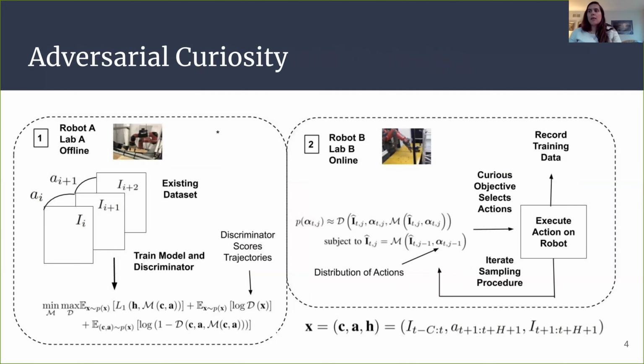As opposed to accomplishing a manipulation task, the goal of our variant to this pipeline is to sample the environment in order to find data which can be used to improve our prediction model. First, the video prediction model we use is pre-trained jointly with our discriminator. Then, the sampled actions are drawn from a probability distribution approximated by how unrealistic the resulting model predictions are based on the discriminator scores. The sampled actions are evaluated using the discriminator, and the most unrealistic action sequence is taken.